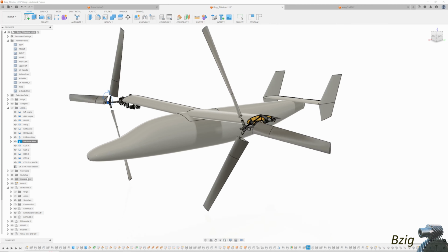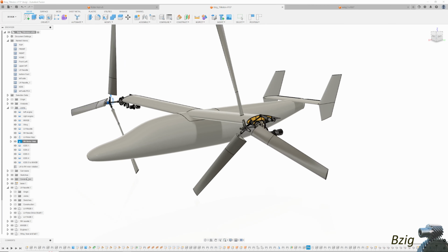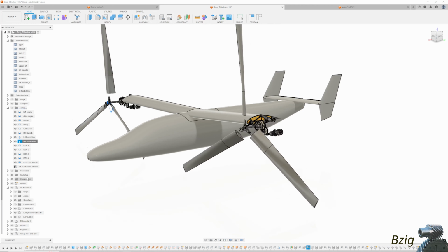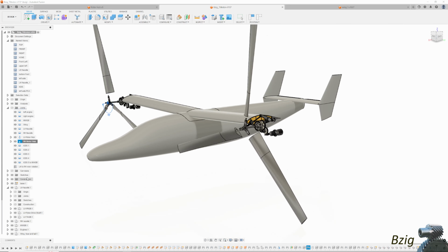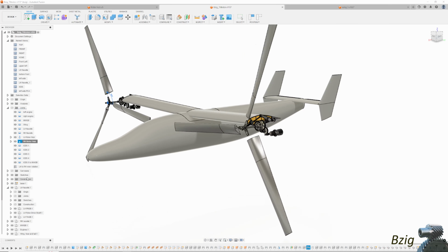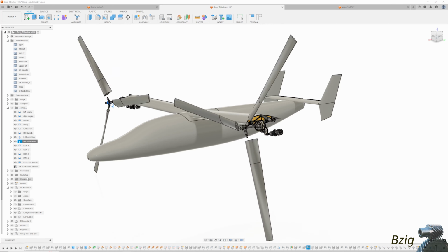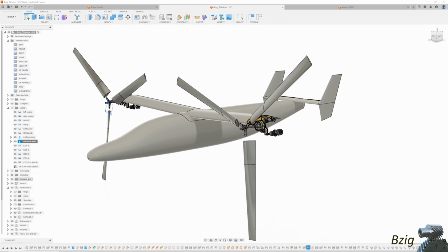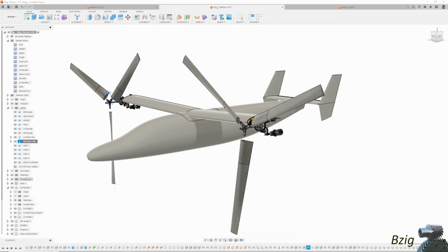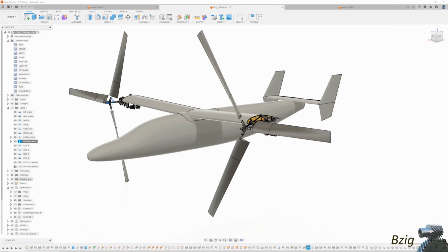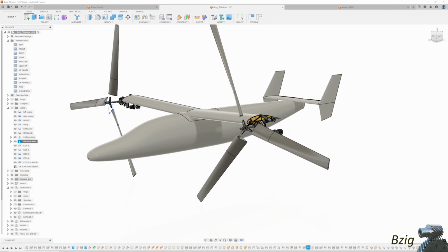Power is provided to the rotors in all engine-out flight by autorotative forces on the blades. Unlike airplanes, tilt-rotor pilots don't feather their props when an engine fails. These rotors always turn in flight. Power comes from the engines when they are operating and from autorotative forces during all engine-out flight.